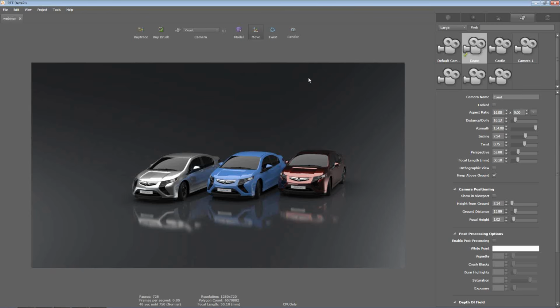You can also add emissive materials, giving you Light Studio-like control, not to be confused with the HDR Light Studio software, by adding, for example, planes and giving them an emissive material so that they shed light into the scene. But the basic directional, point, and spotlights are there, as you are very much used to from DeltaGen and other software tools.